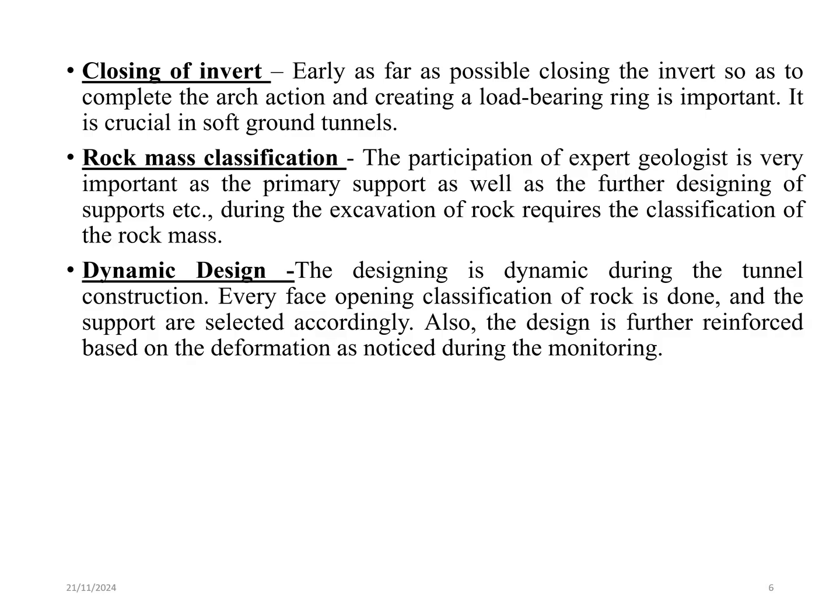The fifth principle is closing of the invert. Early closing of the invert is done to complete the arch action and create a load-bearing ring, which is crucial in soft ground tunnels. The sixth one is rock mass classification. Expert geologists classify the rock mass during excavation to determine the primary support and further design support.